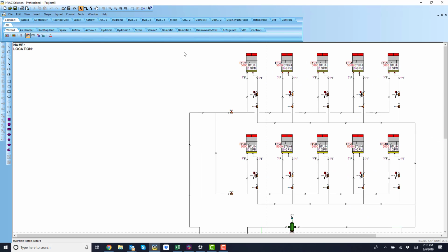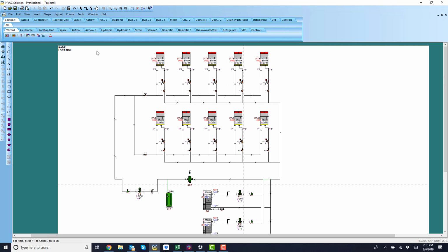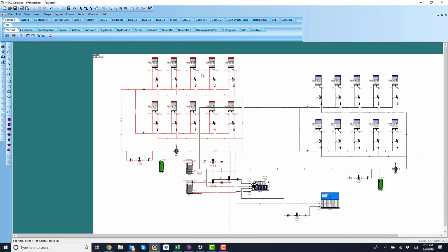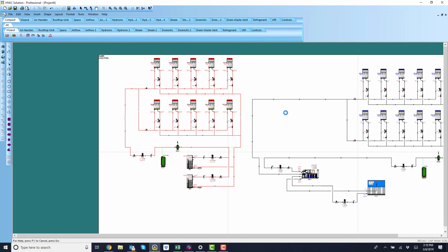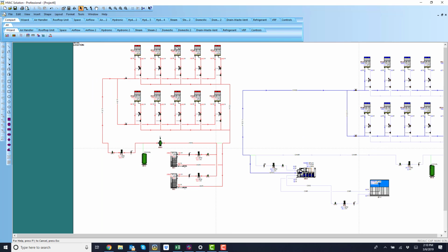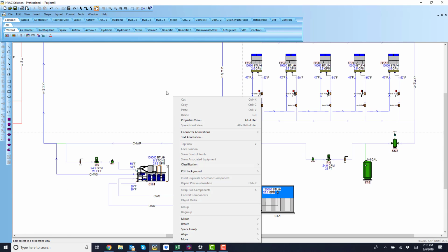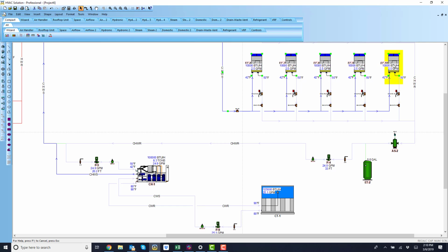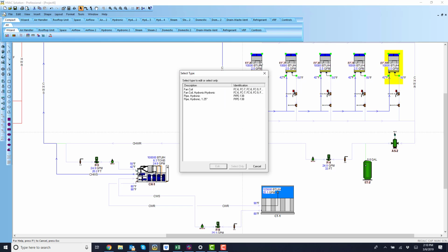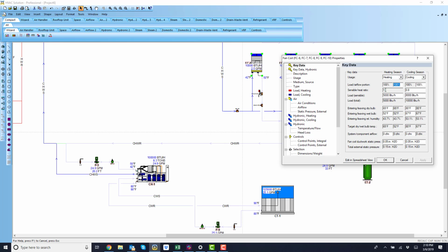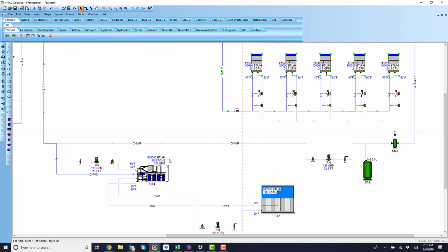When you hit finish here, you're going to see our 2 boiler hydronic hot water schematic, our water cooled chiller schematic there. Let's pan in over here. 8.3 tons. Obviously, if anything changes in the system, right? If all these loads they go in, fan coil, let's add a 0 to all those. 80,000 BTUs of cooling now. Okay, now we're 45.8 tons.